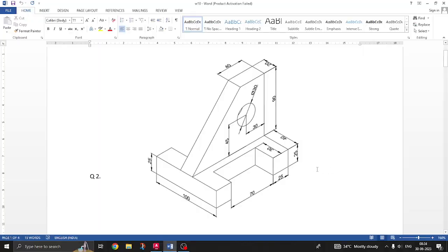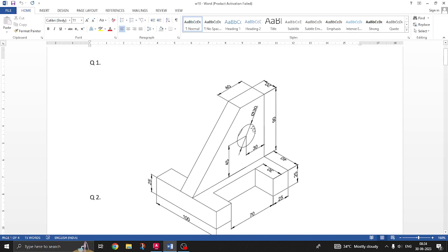somewhat it is completed. Okay, now coming to this circle, actually this whole is a circle. In this view it can be visible as a circle, but in the isometric view it will be an ellipse. Okay, so this circle center should be 30 mm and 45 mm from the bottom, or above 45. Okay, because this is 90, from the middle it will be there, in the horizontal 30 mm. Okay, let us draw